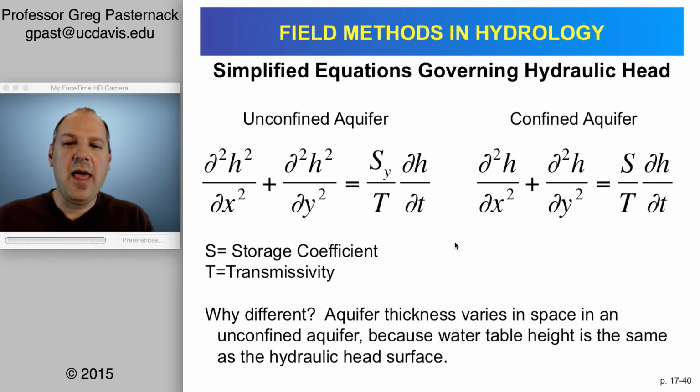In any case, the purpose of these two equations is to allow you to predict the hydraulic head anywhere across the landscape. And all you have to know are any inflows or outflows, of course, anything weird like that. But within a closed system, you just have to know the storativity and the transmissivity that's present there.